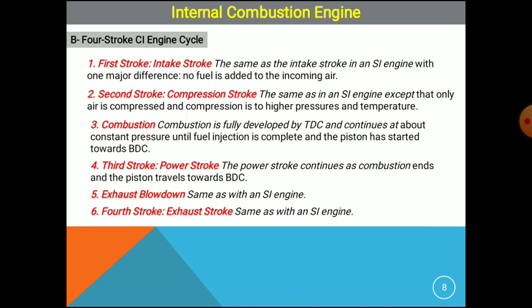Then the combustion process is fully developed at the top dead center, and it continues at constant pressure until the fuel injection is complete and the piston has started towards the bottom dead center. Similarly, the third stroke is nothing but the power stroke. The power stroke continues as the combustion ends and the piston travels towards the bottom dead center.